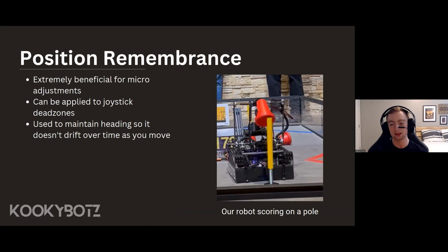A simple fix to this that completely negates the issue with micro adjustments is just always caching the heading value you are setting to the modules. As soon as you detect that the joystick goes back to 0, your dead zone, meaning that you've let go of the joystick, you write back that same cached heading value to the modules. This means that heading will be maintained all the time until you rotate the modules yourself. This same concept can be applied to heading on the robot, making it easier for the swerve to maintain its heading around the field when translating and rotating.